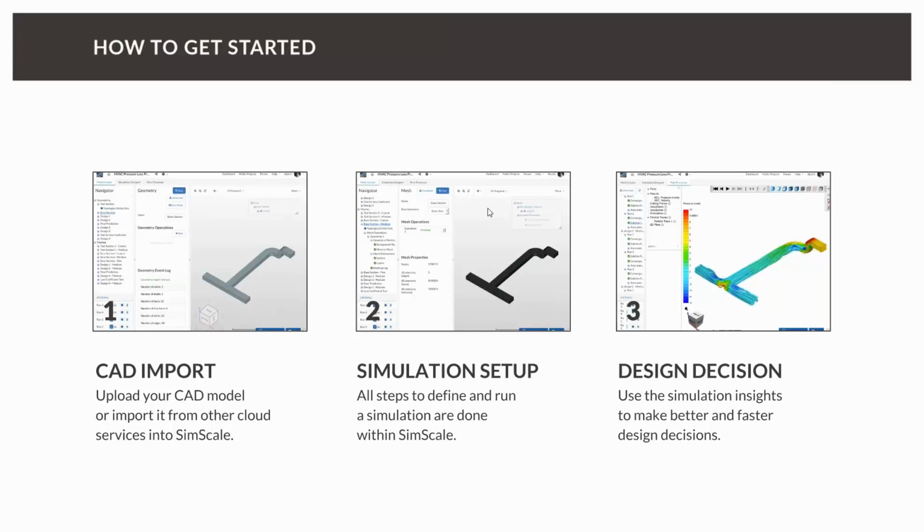In contrast to manufacturing, where we need a model representing the material of the ducting system itself, for our CFD simulation we need a CAD model which is representing the fluid domain. So we need a CAD model which includes the space inside our ducting system.